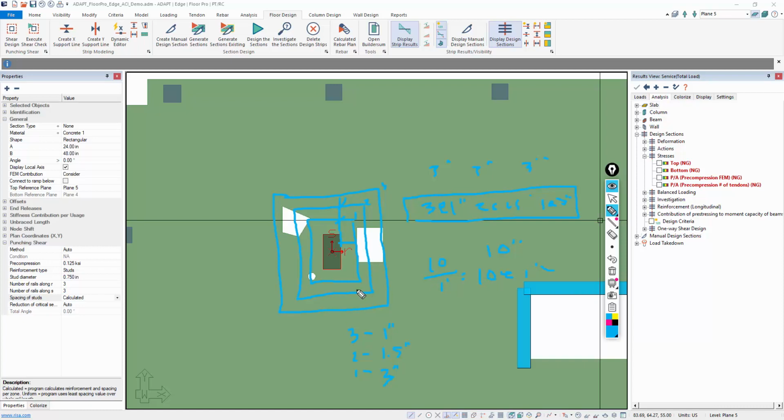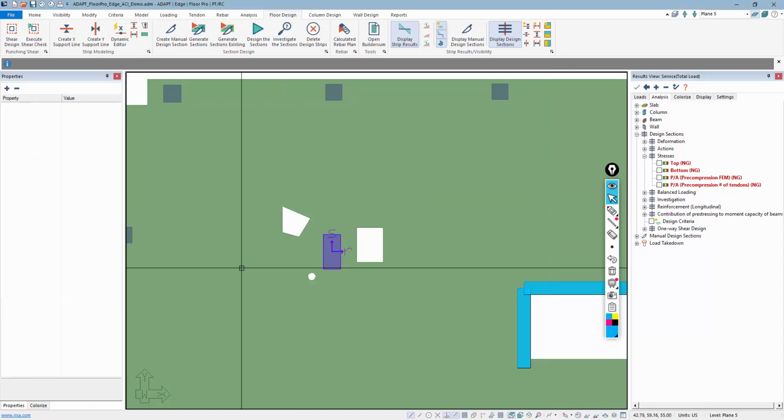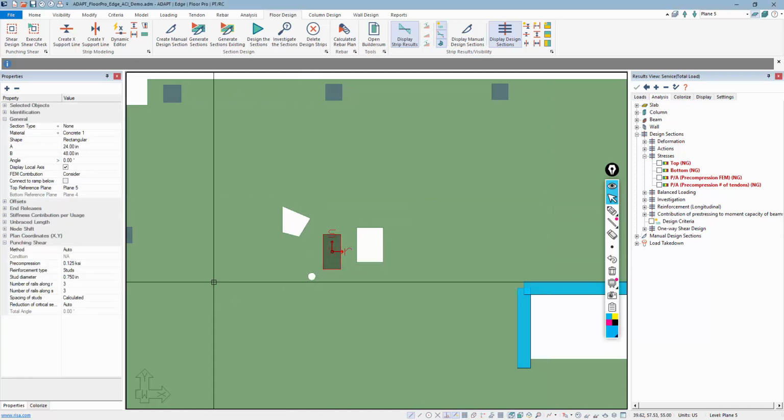And that's because the program is simply post-processing the output results versus running the solution again, assuming some uniformly spaced arrangement of studs. That is coming in a later version, but currently that is how uniform spacing is being calculated in the program. It's post-processing the output that's already been done per the calculated method.